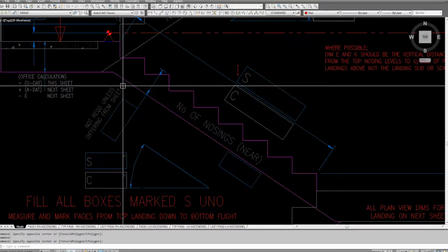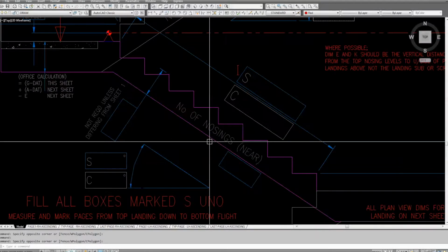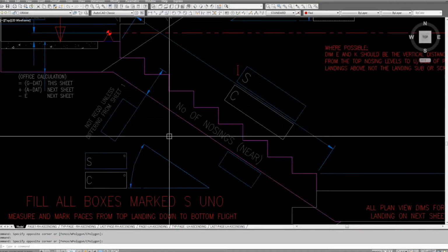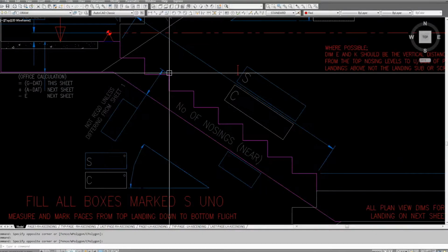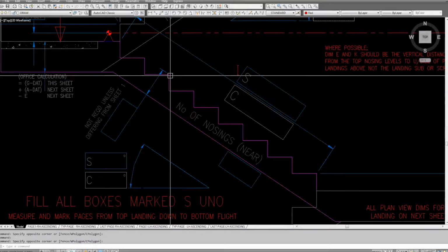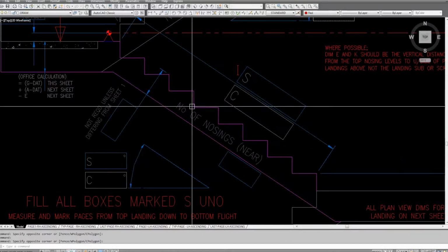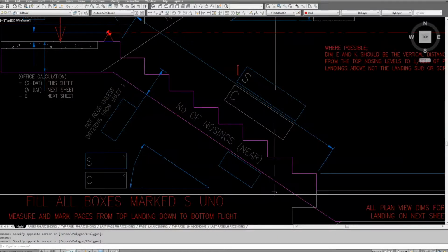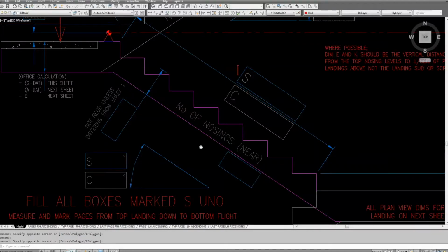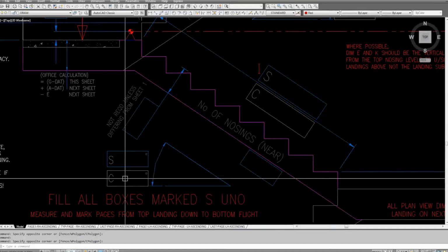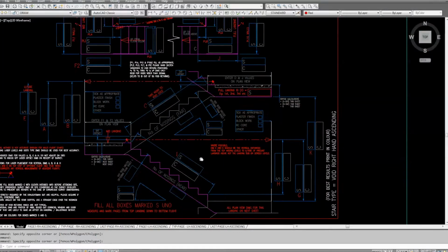Another thing I've noticed is that some guys put their angle finder on the soffit. That is a really, really bad practice, because you won't believe how badly cast some of these stairs can be. So that dimension there can vary between top and bottom of a flight. So it's a false reading anyway. And the only reason I put it in, if I've got time, is it's just a cross reference.